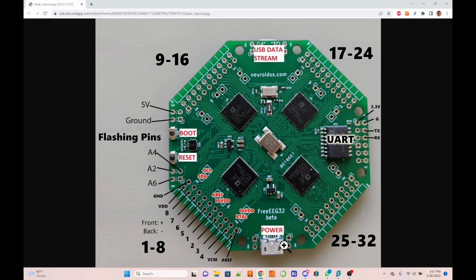The reason we have separated power is to have a very low noise system. And on the back side of the board there's actually a DC to DC transformer to completely isolate any noise that might come from the power cable. So it's this split system of two USB cables. Although it's a nuisance having two USB cables, this is one of the things that makes this a quality system, because you have a complete separation of noisy power.